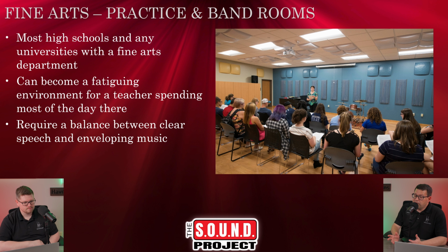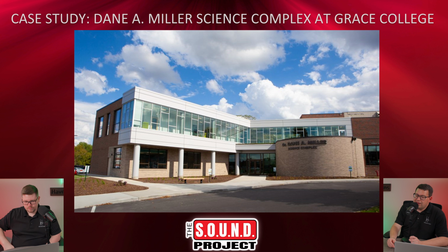And this is one of their ensemble rooms that has some Flex 48 panels from Acoustical Fulfillment on the walls, and then some geofusers from Orlex on the ceilings and the walls, just to make a nice environment that's mostly diffuse, but they could also take those shields off of the Flex 48s and make it more dead sounding if they want, depending on what they're doing on a given day. But these rooms are really important to make sure it's controlled enough that practice is fruitful, and allows them to sound their best.